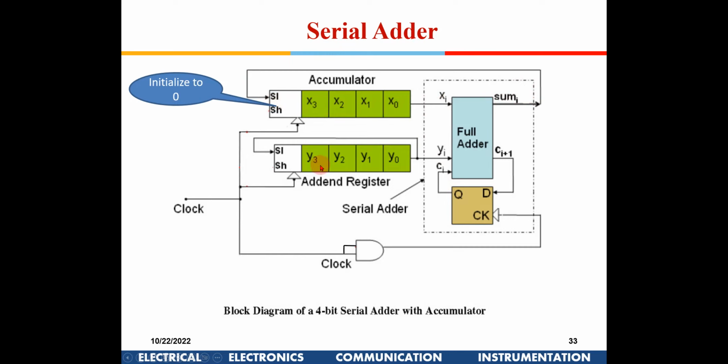In the bottom register, the carry will come here as well. After 4 clocks, this data will come here, and since you have initialized both these registers with 0, 0 0 will be available here, but the carry from the 4th bit addition will be available here.